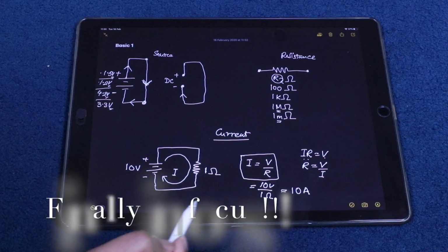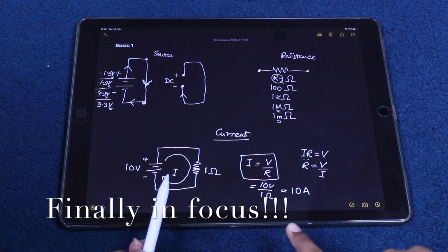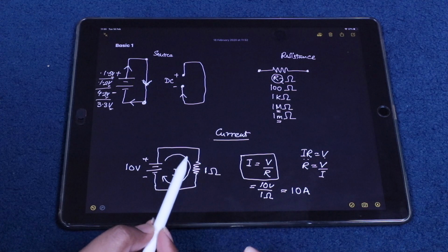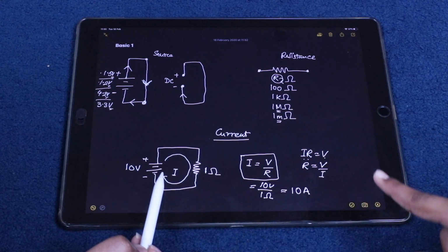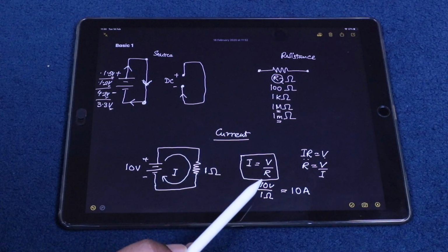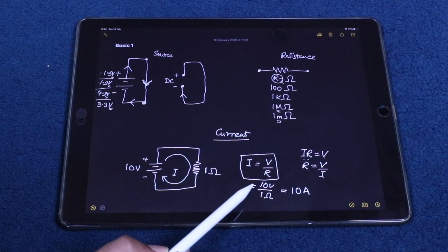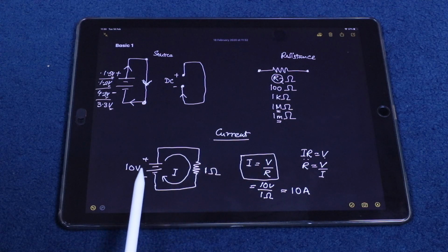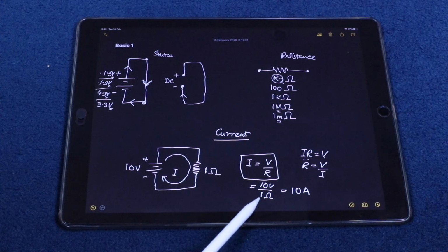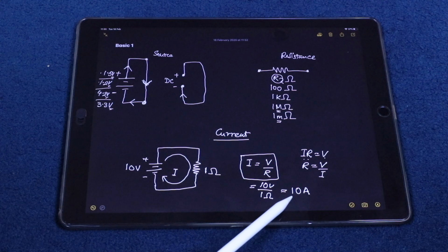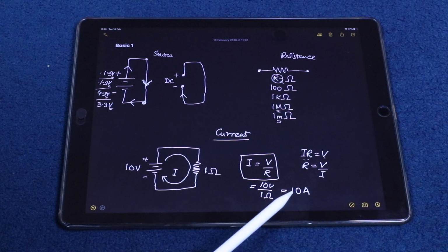All right, so questions? So is it allowing all the voltage through? The current through. Yeah, all the current through. So look at this formula. Here we had 10 volts. Let's keep the voltage the same. And the resistance, now, it was 1 ohm. If this goes up, say it becomes 10 ohms, what happens to the current? It'll go down. It'll become 1 amp. Yeah, 1 ampere.